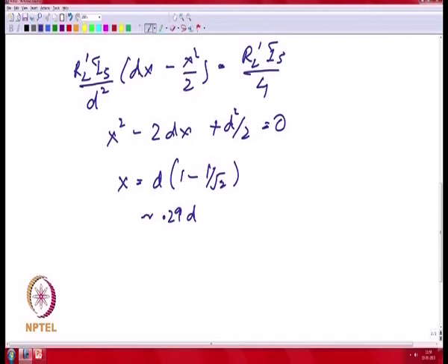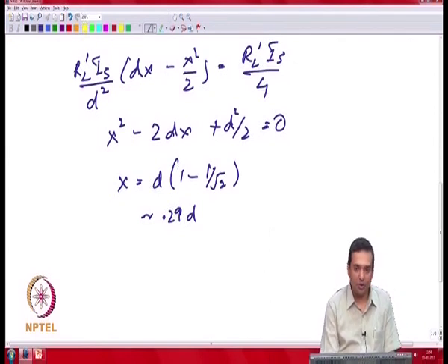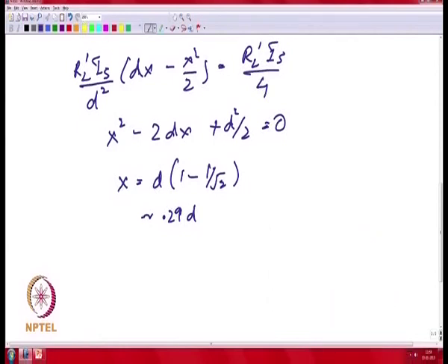Again, this is assuming that you are having uniform loading. You are also assuming that your power factor is the same across the loads on the feeders, but this gives you a feel for the nature of the requirement to maintain the voltage along the feeder.